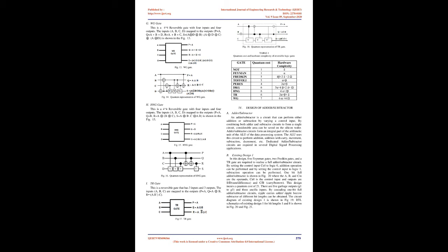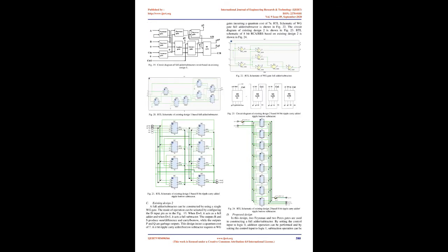For example, assuming that all the 1.75 billion transistors in a processor, for example an Intel i5 core, dissipate heat at a rate equal to the processor's operating frequency, 2.5 GHz, then the processor would consume a power of approximately 2.5 times 10^9 x kT ln2 x 1.75 times 10^9 equals 12.258 MW, assuming that the room temperature is 300 K. The loss incurred is not tolerable in the design of ultra-low power consuming devices.